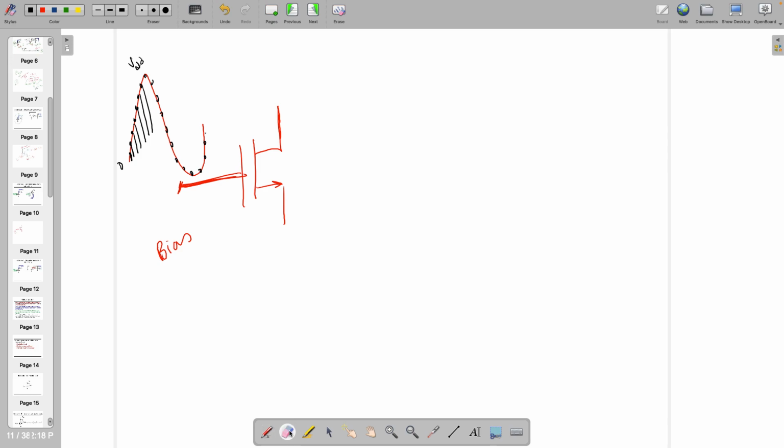Nobody is stopping that. But bias is the potential which is going to make sure that your transistor is in a particular region of operation. I am writing this with DC just to make sure that whatever bias I am giving, it's DC bias. Generally bias is DC. However, it's not compulsory that it has to be only DC. AC can also bias the circuit with the available voltage. Okay. So I applied here DC bias.